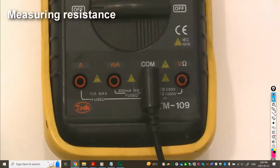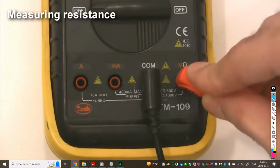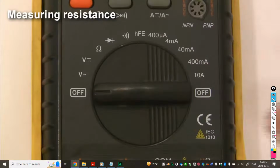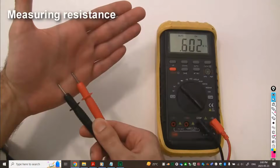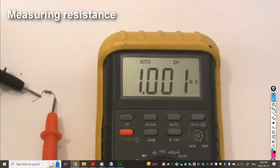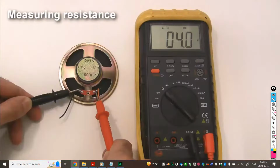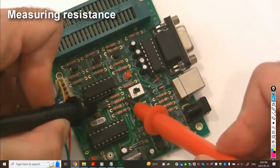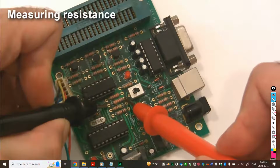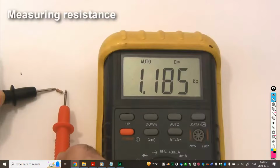Measuring resistance is easy too. Make sure the red lead is in the jack labeled ohms for resistance, and set the dial to the resistance setting. Here is me measuring the resistance of the skin on my hand. Here's me measuring the resistance of a resistor. And here I am measuring the resistance of a speaker. Now you might be wondering if you can measure the resistance of something in a circuit. Well, unfortunately it most likely won't work. You're going to have to remove the resistor from the circuit before measuring it.